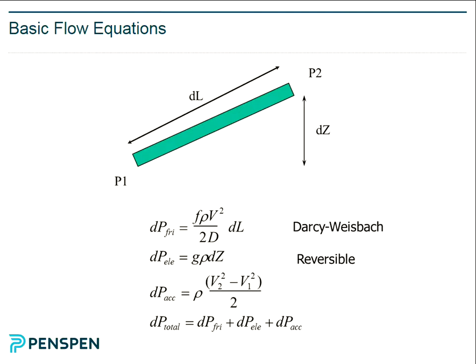So Reynolds number, if it's less than 2,000, we call that laminar flow. Greater than 2,000, turbulent flow. So laminar flow is literally laminations. It's all moving together along the pipeline, like in stripes. Turbulent is as it describes. It's a complete mess. Each particle trace will be almost random. Turbulent flow is actually more efficient. Laminar is actually a very efficient way of flowing.